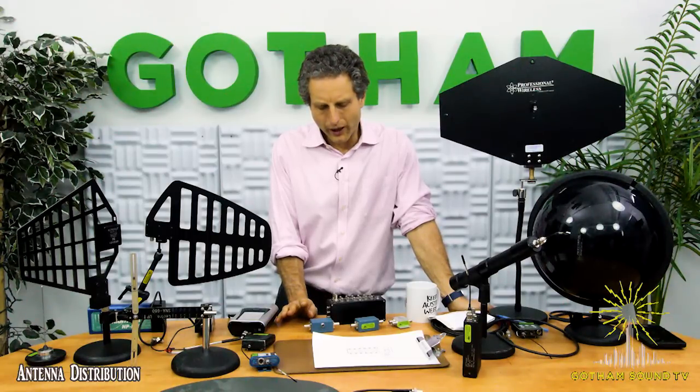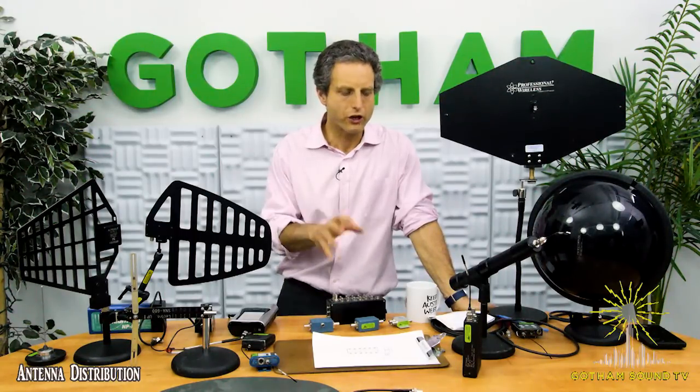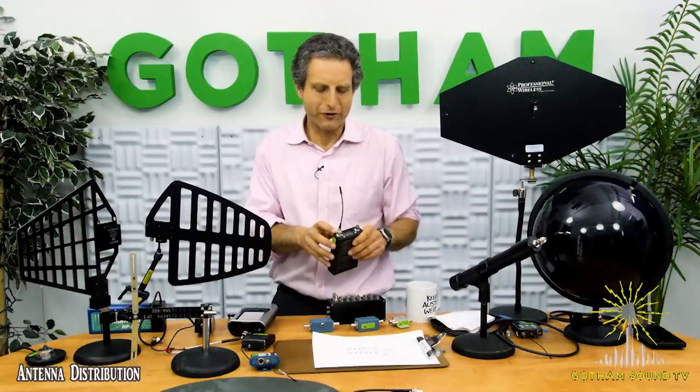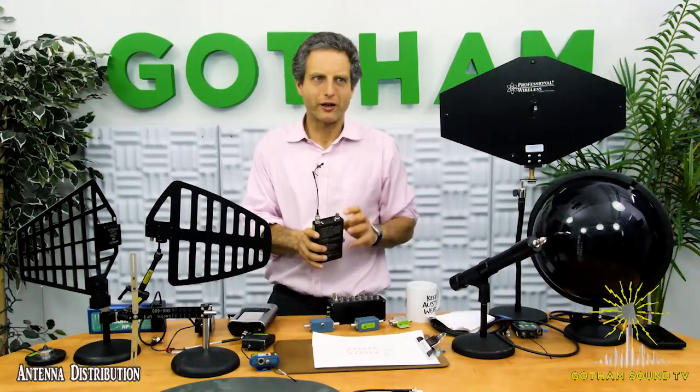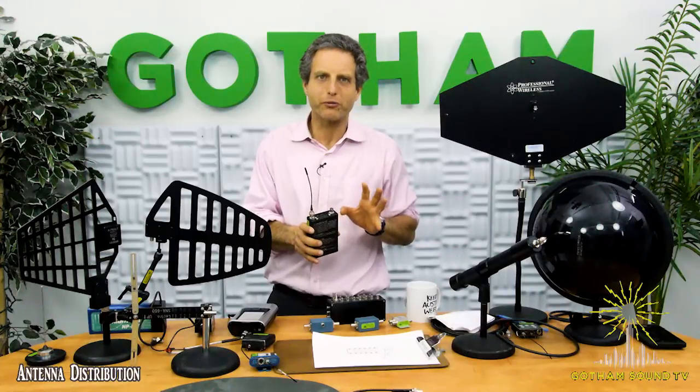So I think we have to talk a little bit about RF theory. One of the issues when you have a bunch of receivers with their antennas really close together is that in order for a receiver to be on frequency, it needs an oscillator of its own. In an ideal design, the internal frequencies will never become external frequencies, but receivers can become very, very small transmitters.